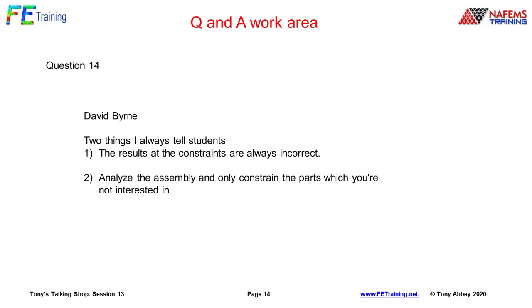The only trouble with that, David, is that sometimes it's like the knee bone's connected to the thigh bone and so on. We end up modeling a lot of assembly to get to that point. I've come into big problems there with US Navy DDAM analysis, where we're just looking at local deck regions, looking at shock loading. We want to basically look at normal modes analysis of that region, then do a shock spectral analysis on it. We're not sure of the boundary conditions there. We model the next piece of deck and so on.